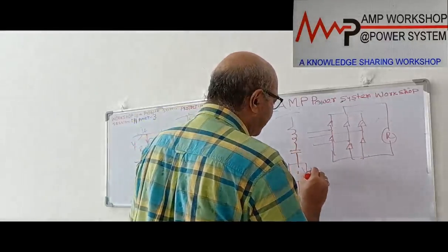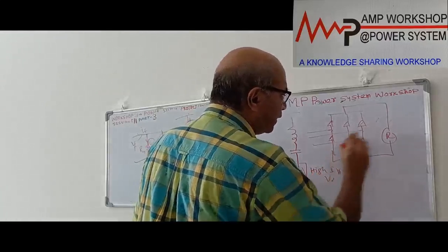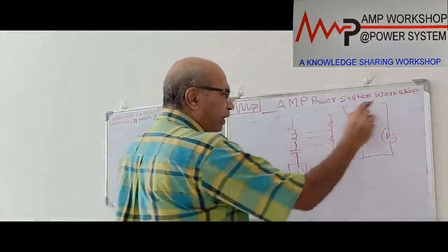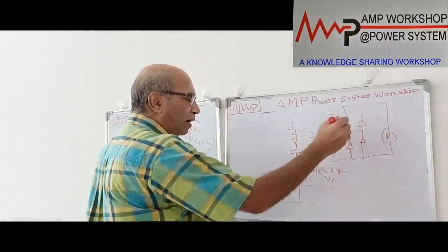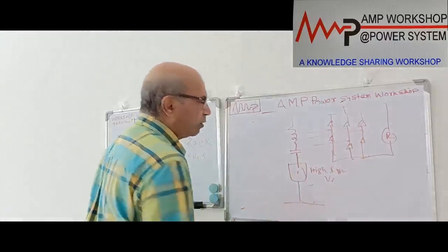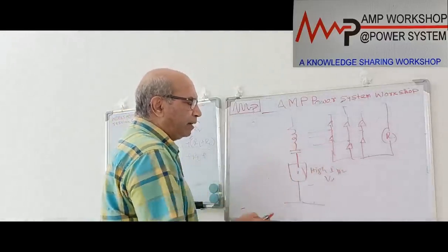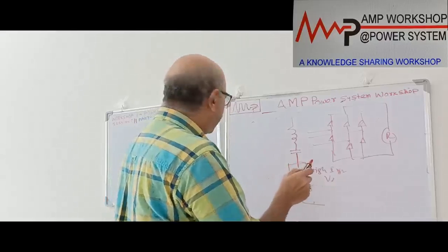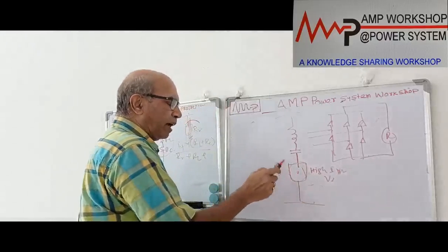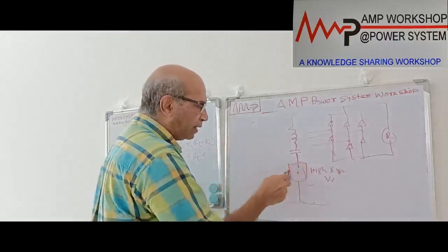Now this is a high impedance voltage balance relay. This relay operates as a DC relay, and this is one of the manufacturers' designs. Why is the high impedance relay made this way? First of all, it is a high impedance relay, so in an abnormal unbalanced condition such as CT mismatch, very little current will go through it.